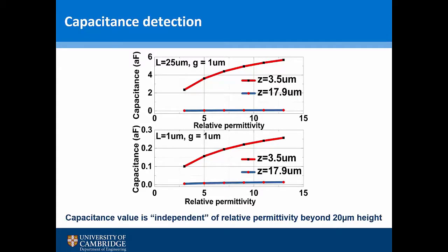And this also explains why the collision method, which is the deposition method, is the best instead of having an inflow detection. One of the things I think people have tried in the past is an inflow detection model where instead of forcing the particles to deposit on the electrodes, you just make them flow above the electrodes. But if you wanted to design such a system, you would need to make the particles flow as close as 3.5 microns above the electrodes without deposition, which can be hard.